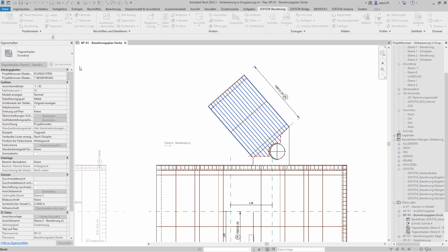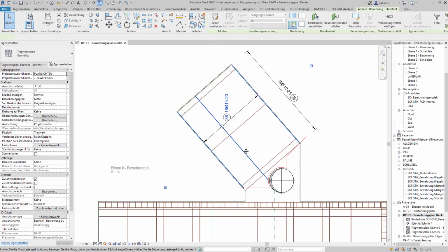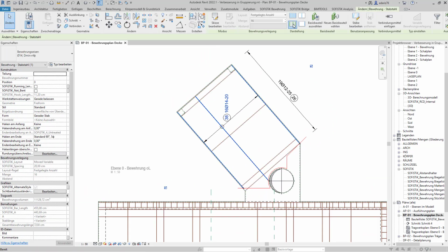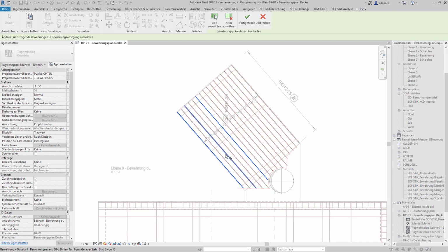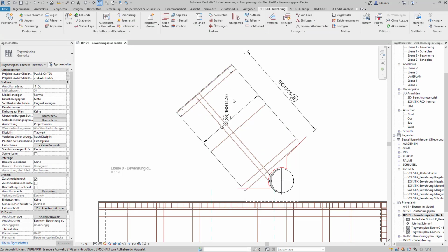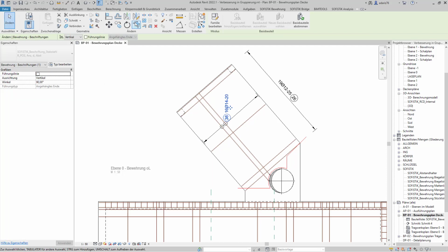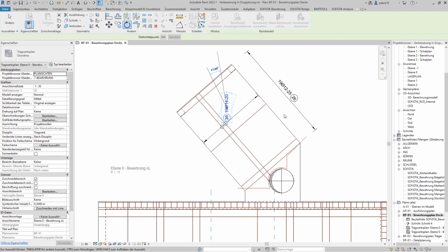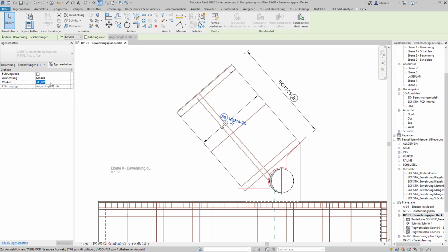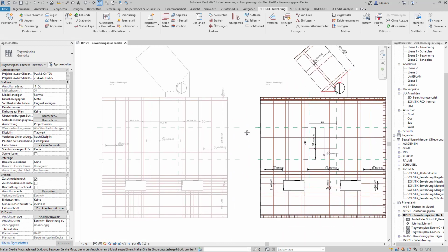This also opens new possibilities for labeling. For the hide and tag command, we no longer need a detail element that we have to laboriously hang on the rebar elements. That increases the performance enormously. You can now use the native Revit functions for hiding individual bars of the layout and hide any number of rebars or isolate them accordingly. This ensures that your drawings are easy to read.